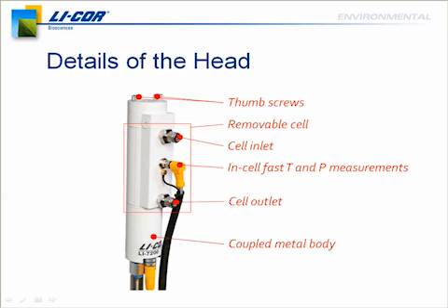Okay, Martin. The optics of this analyzer have a very low sensitivity to contamination, especially if you compare it to other closed path laser-based platforms. The 7200 is like the 7500. It has an automatic gain control feedback loop, and this allows you to boost the signal for partial blockages. And this allows measurements to continue even with a slight contamination.